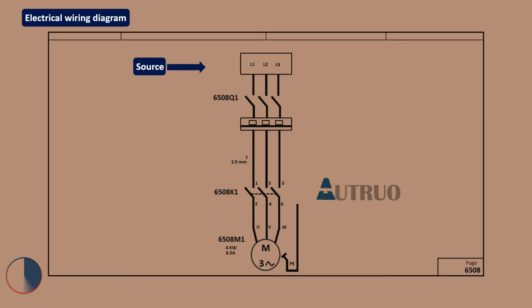Again, the power configuration is stated in accordance with the country's power ratings. So from the source, current will flow from the top half of the schematic to the breaker. By default, all components are usually in their de-energized state, and as such, this device is not an exception. From the breaker to the contactor, before it is finally terminated to the three-phase motor.